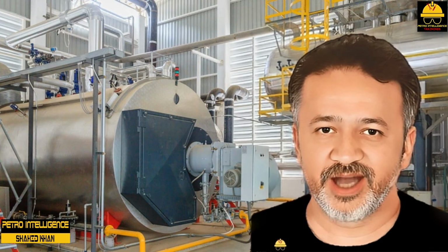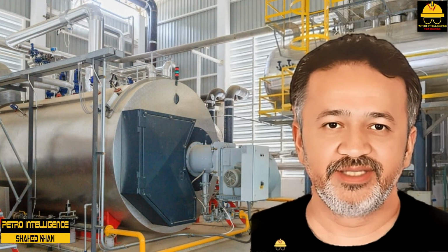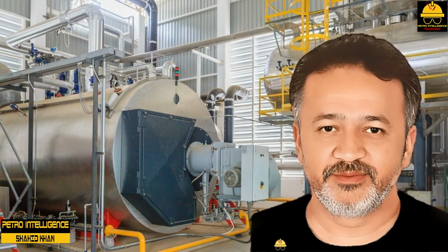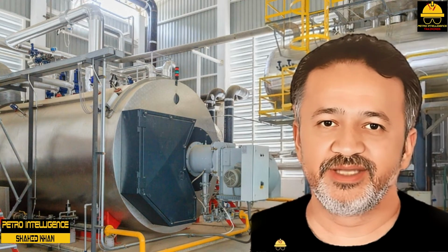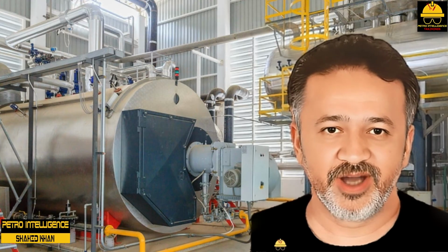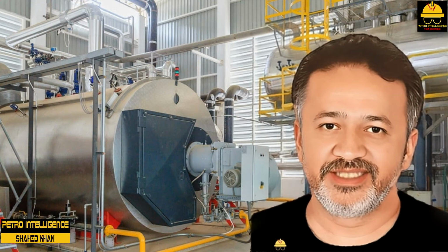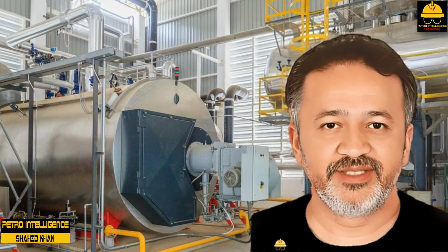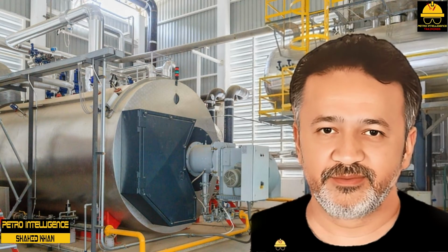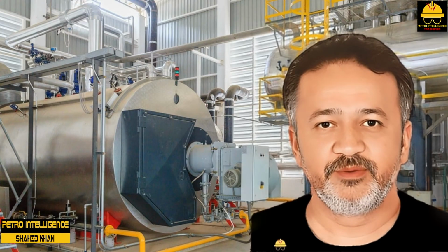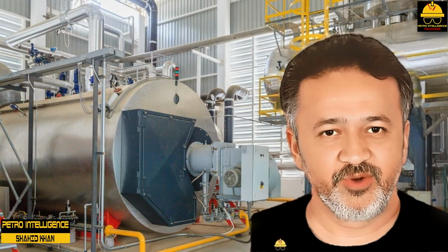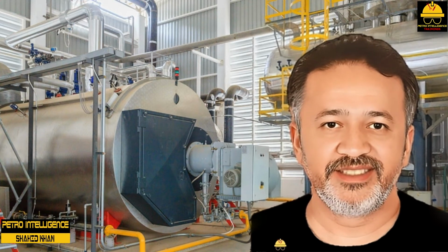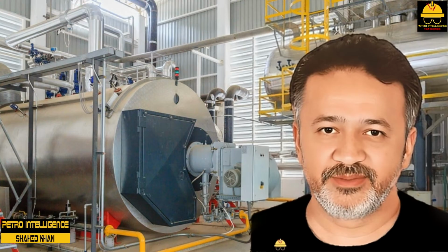Let us discuss now steam. As long as steam and water are in contact with each other, the steam is saturated. This saturated condition means that for every temperature of water, a corresponding pressure of steam exists. The pressure on the water sets the temperature as long as the steam and water are in contact. Basic boiler design removes the steam from the upper steam water drum and heats it up at essentially the same pressure. This process is referred to as superheating.